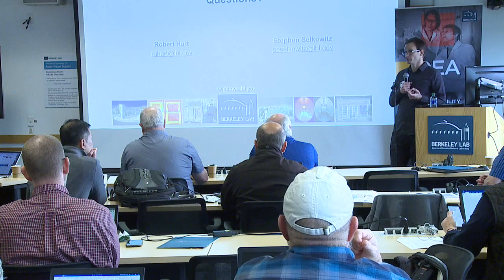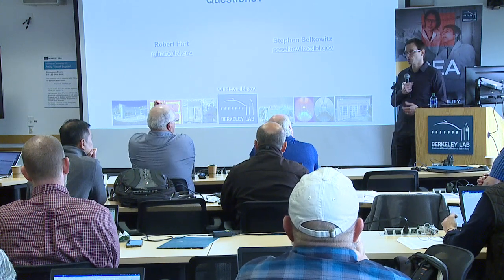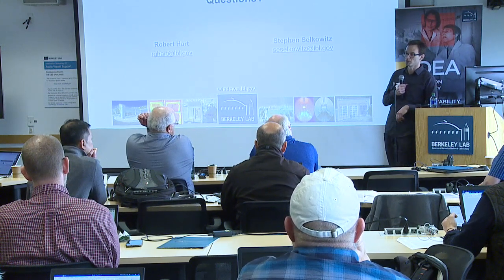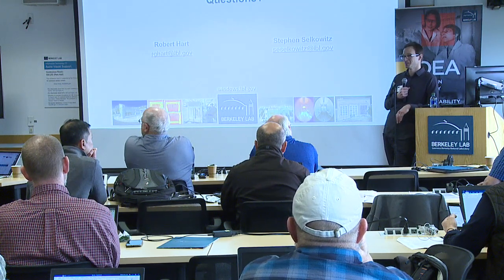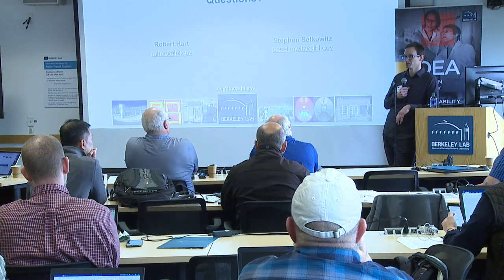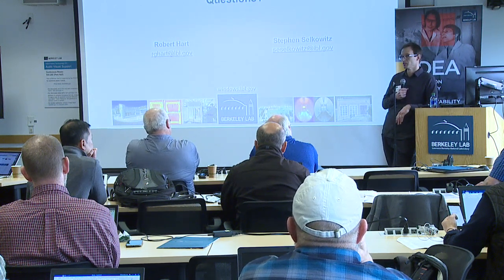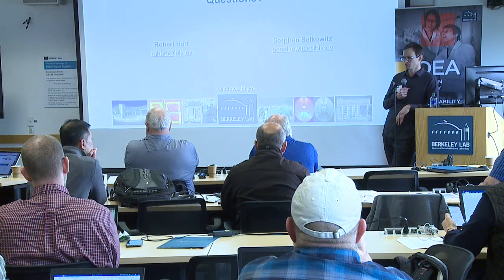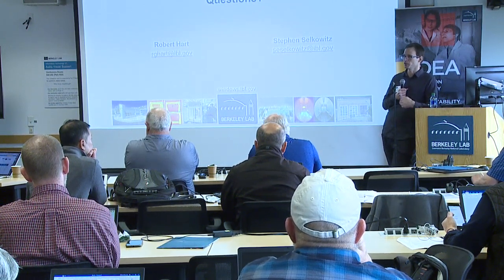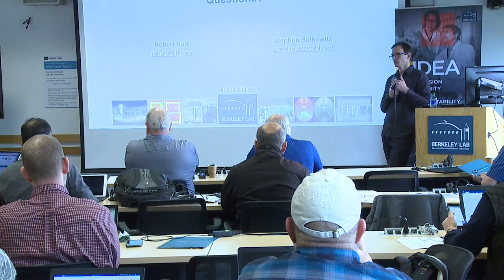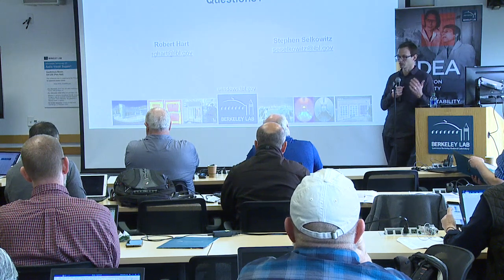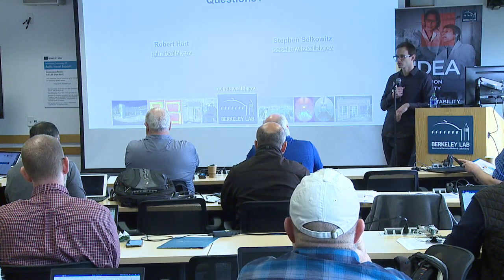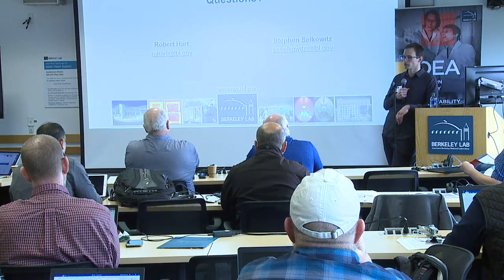The other issue is just seal failure, and that's generally quality of window. If you buy the cheapest window you can buy, you might be more likely to have a sealant failure, because it might not be as good of a window. But the failure rates of some of the big manufacturers, the people that actually track this, the Cardinal IGs of the world, that are the biggest U.S. residential glass or IGU manufacturer, are very low.